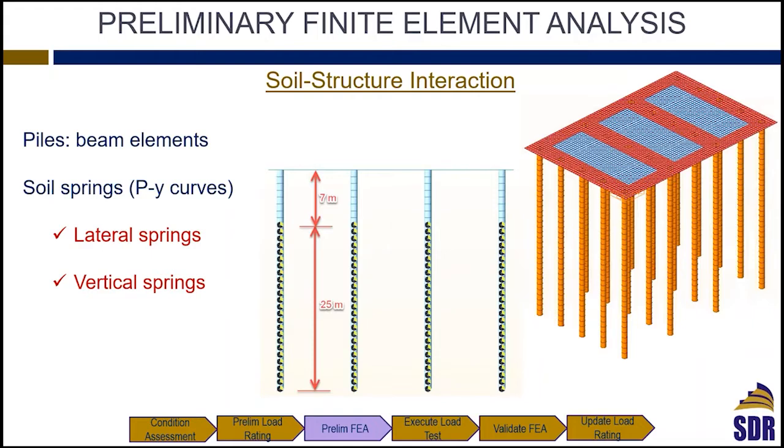When you are modeling a column with a fixed base versus a column where you are modeling the pile and representing the soil, you will expect that the model with the pile and the soil represented will be more flexible, which means you might encounter more deformation, but your internal forces in terms of moments and shears might be significantly less.